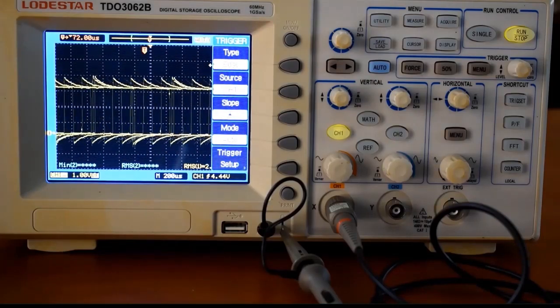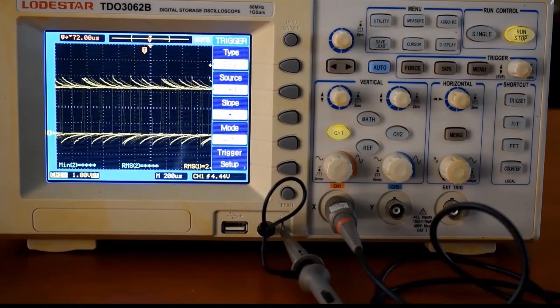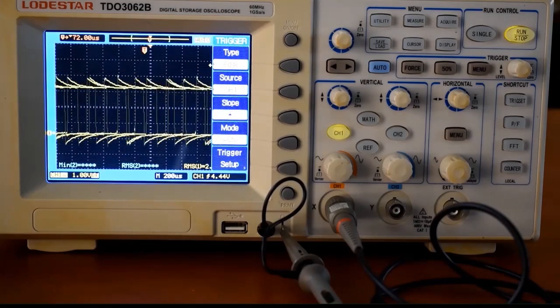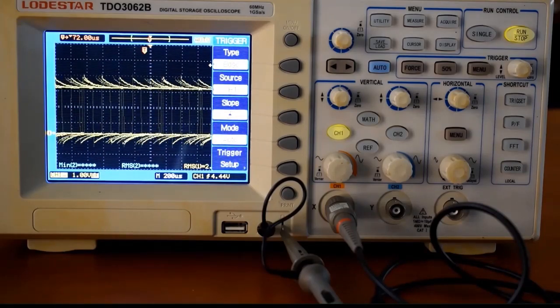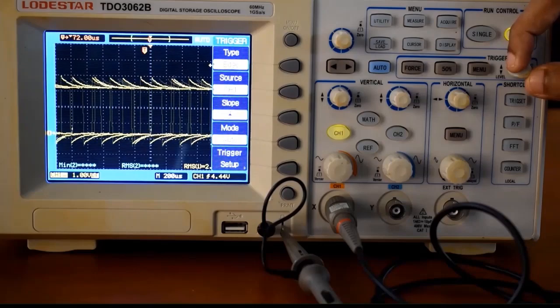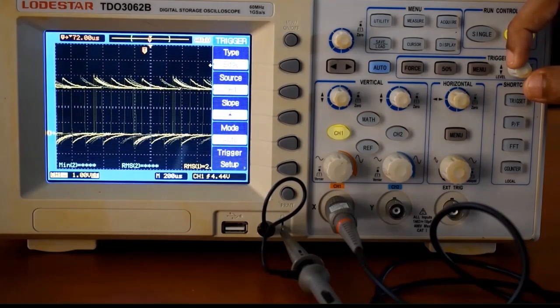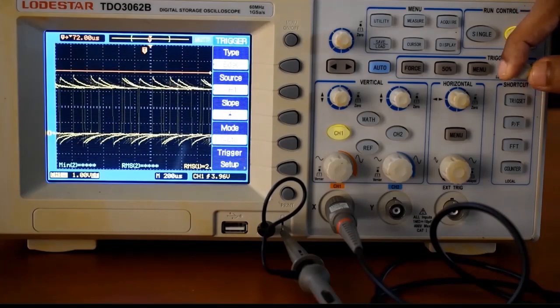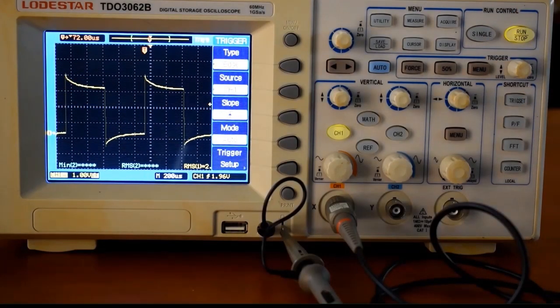If the waveform seems to be moving or jittering, this is because the oscilloscope has no idea when on the waveform to start measuring, but we can fix that by adjusting the trigger level. Use the knob in the trigger section to raise the level to somewhere between the min and max of the waveform. This tells the oscilloscope to begin measuring as soon as it sees a rising edge, perform one sweep on the screen to draw the waveform, and then repeat the process.